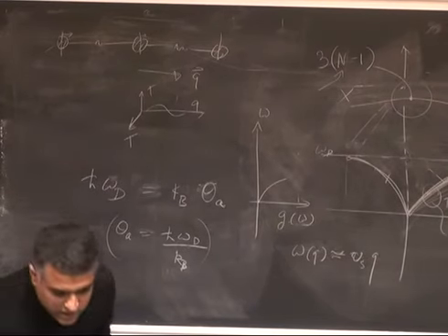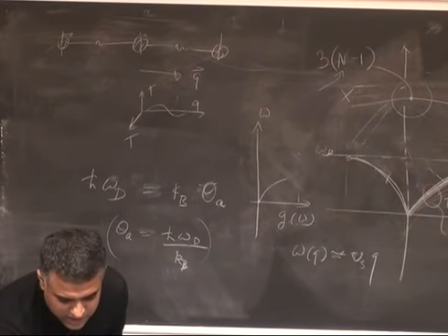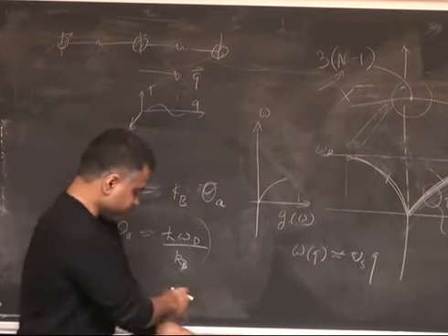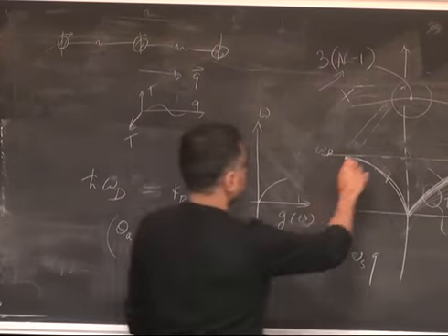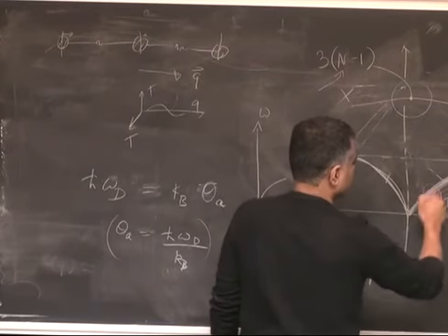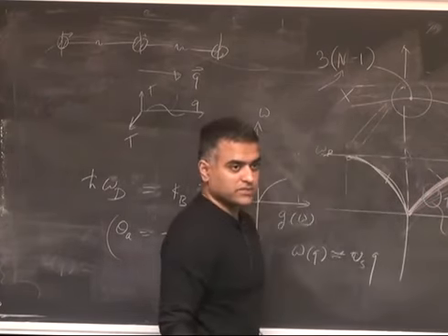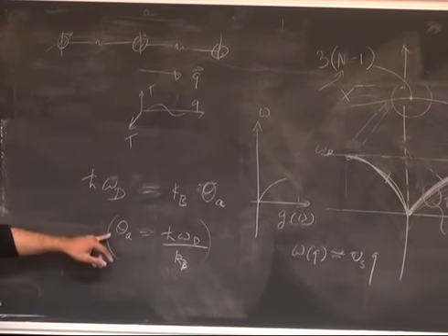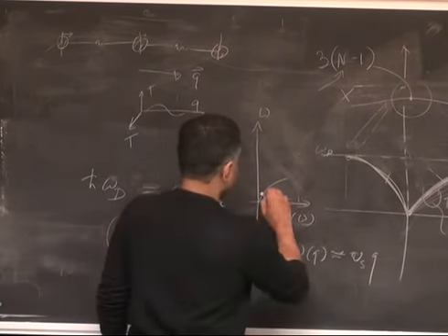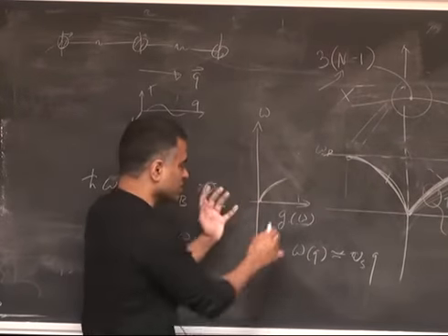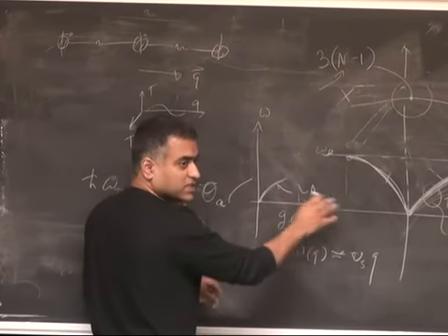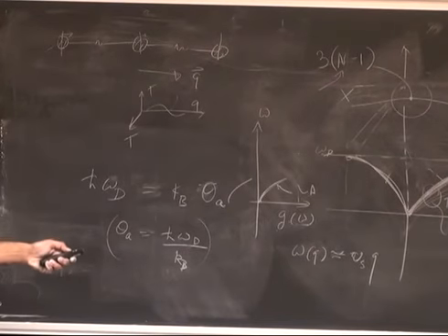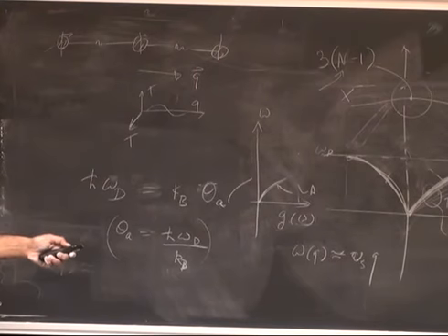So now what you can do is come back to the thermal conductivity picture and say, what if I had, you know, the Debye temperature is clearly defined for a band like this, but then you can have multiple longitudinal and transverse and other modes as well. And you can ask, can I get an effective Debye temperature by including all the details of the bands, by doing a sort of averaging over many of them? So there's a DOS for LA, there's a DOS for TA, and all these other modes. You can do some sort of averaging, which is kind of shown there. You're averaging your Debye temperature with the density of states over many modes.